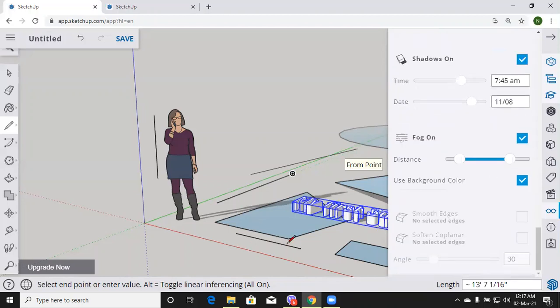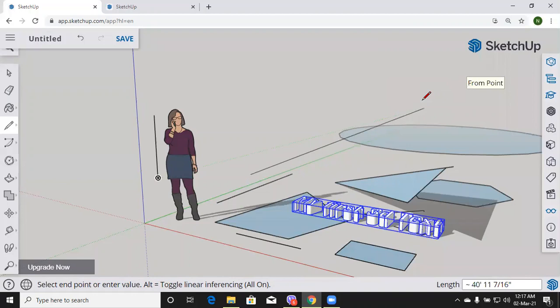Okay, to draw the 3D objects, now let's close this panel. To draw the 3D objects in no time, SketchUp provides the push/pull and the Follow Me tools. With push/pull, you can generate a 3D object by clicking and dragging from its 2D base, defining the extrusion length for it.